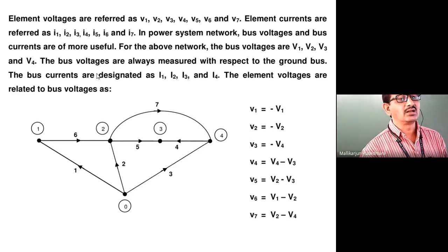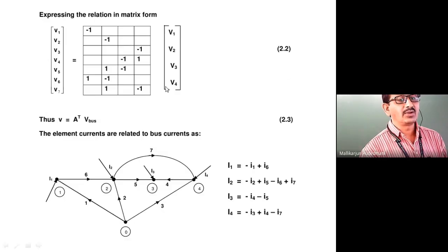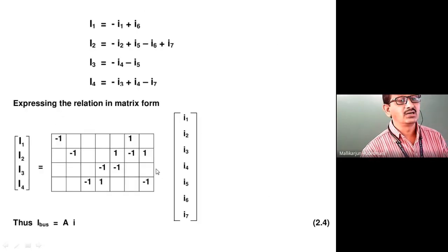And how to write a KCL? That also we have seen. When we apply KCL at this junction, the current incoming must be equal to the current outgoing. So the author has used one new technique. Suppose there is an injection of I1 here, capital I1. Where will it all go? It will go towards 6, getting I1 from this. You can see here, capital I1 is equal to incoming current minus outgoing current. So if you make it 0, minus 1 if you take the other side, incoming current must be equal to outgoing current. In this way we can do it. Okay. This is how this was seen in the earlier class.